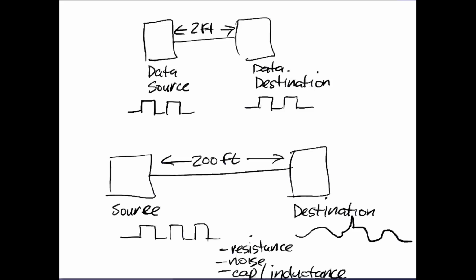So if we were to think of just connecting a voltage signal from a data source to a data destination, for those of you who completed the ELTR 232 electronics course, when you went into digital and you were using those trainer boards, you connected ones and zeros like this from one gate to another on that trainer board, to maybe a maximum of 2 feet, over a couple of copper wires, and that worked. We had a voltage input signal being detected by the gate that was receiving the signal, and it was easily able to interpret that voltage as between 0 and about 1 volt, and between 2 volts and 5 volts, to retrieve the information, to interpret the ones and zeros.